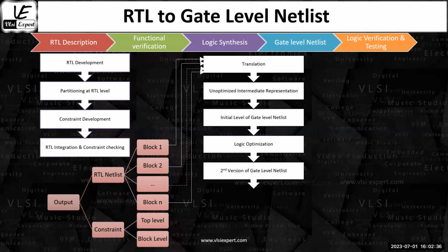So that means when you are talking about logic synthesis, first it will convert your code into a first level of circuit. Then it will logically optimize it, and it will give you the second level of gate level netlist. That becomes basically your final netlist, not the final, the pre-final netlist.